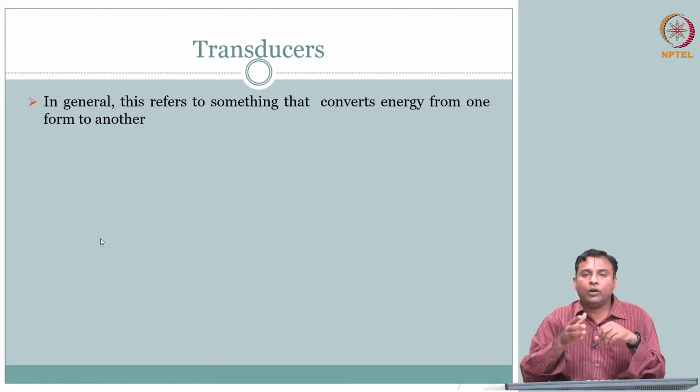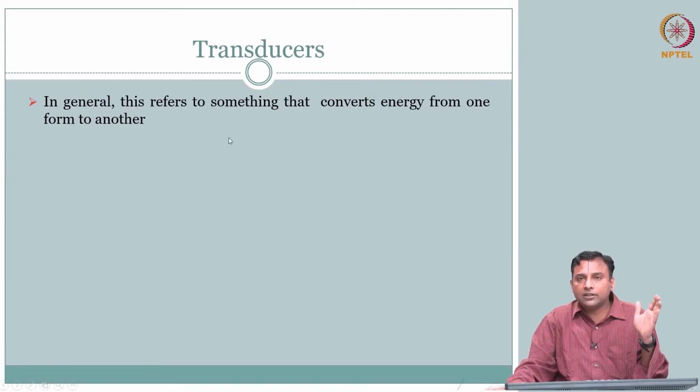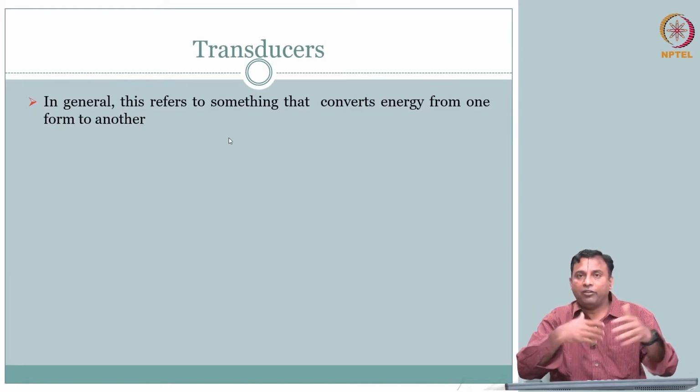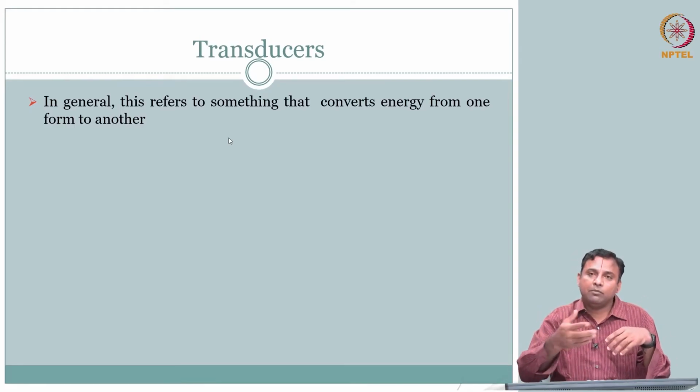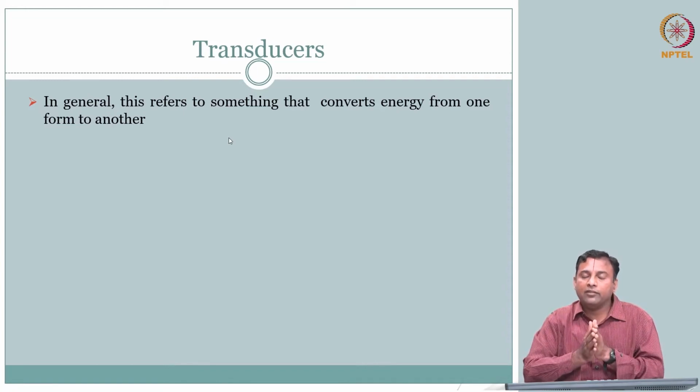So, the idea is I want to generate the sound waves, send them into the body and receive the sound waves. A transducer is something that just converts energy from one form to another. But in our case, what do we want? I want to send pressure waves into the body. The pressure wave gets reflected, bounced back as we saw, comes back, and then you are recording it, you are detecting it with the receiver.